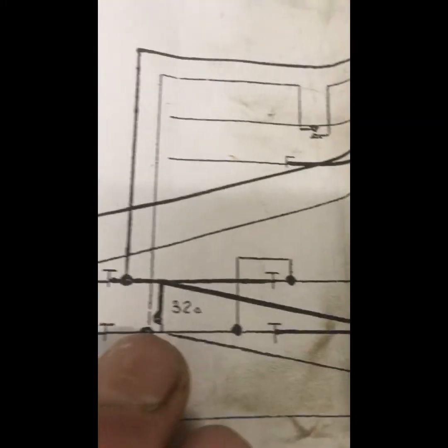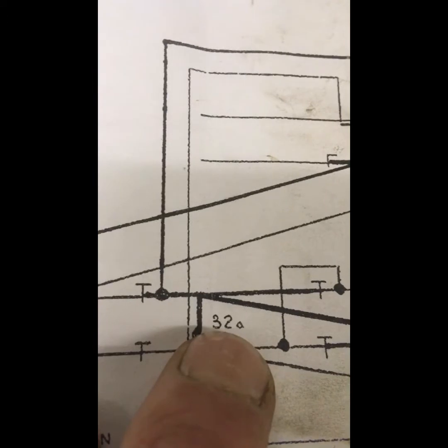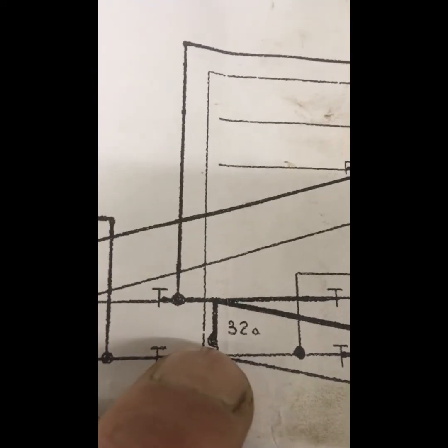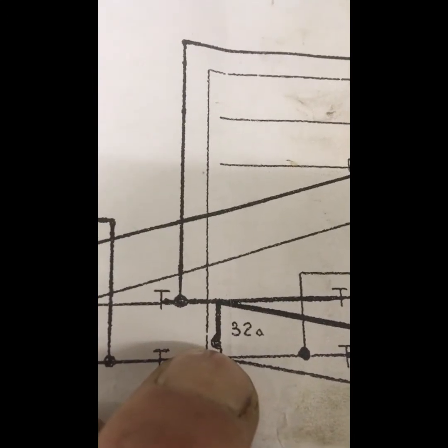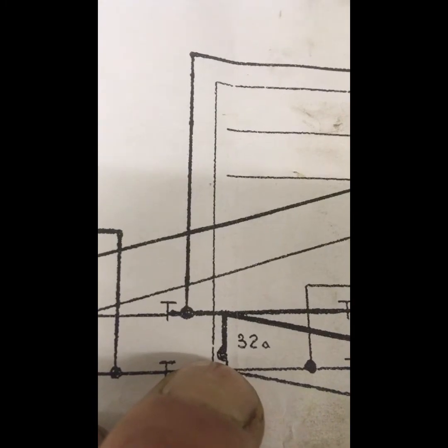Another thing to notice, in this diagram in particular, it shows you the insulations on the points, generalised. So for instance, on these set of points here, 32 alphas, that half semicircle there defines the insulations within the points themselves. It should be taken as obvious that there's insulations on the points. However, they're included on the track circuit diagram for faulting purposes.